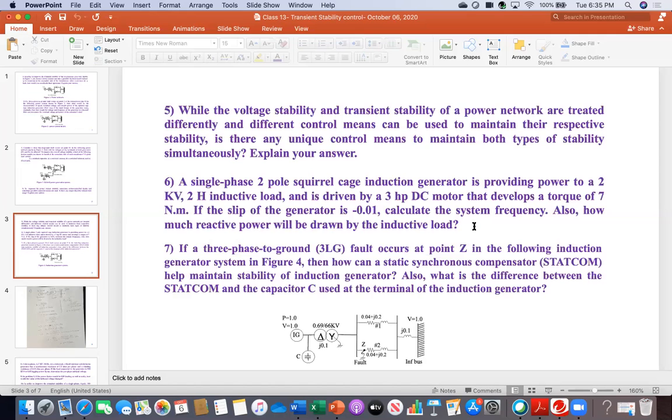Lakshmi, did you get the frequency? Yes, Dr. Ali, I got the same values. The 50.38, okay. 50.39, and XL and Q I got the values. Okay, and then how much is the QL reactive power? 6318. Oh, 6.18 kilovar. Because it is Q, the unit should be kilovar. Oh, okay.